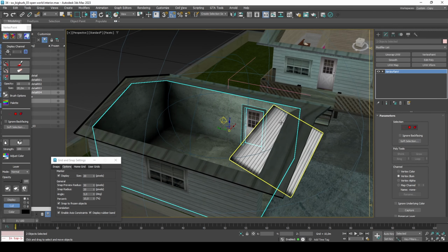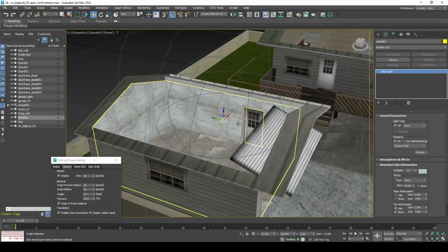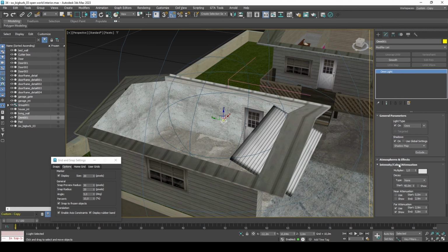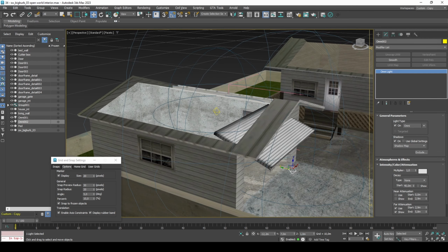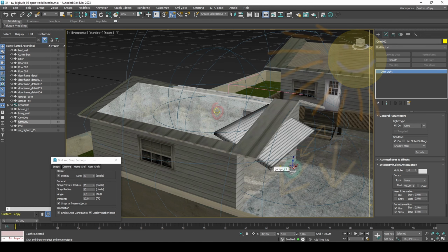Let's also create a pre-light for the day. Display vertex color channel. Set light saturation to 0 and value to 190. Create a copy of the light. Position it at -12.2, 7, 1. This light acts as direct lighting, whereas the one inside the interior acts as indirect lighting when light hits the surface and reflects onto other surfaces.